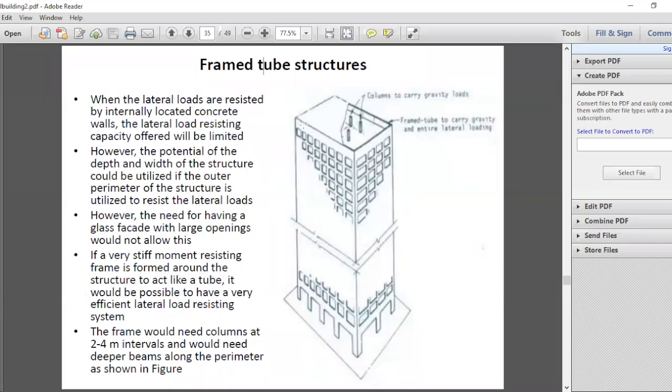And that's why, even in reinforced concrete design, when you are designing a flanged beam, we calculate the effective width of the flange. Can you remember? Let's say we have a slab which acts with the beam, and the spacing between beams is 4 meters, then we don't say the width of the flange is 4 meters. We say the width of the flange is, say, something like 1.2 or 1.4 meters. What is the reason? The reason is shear lag.